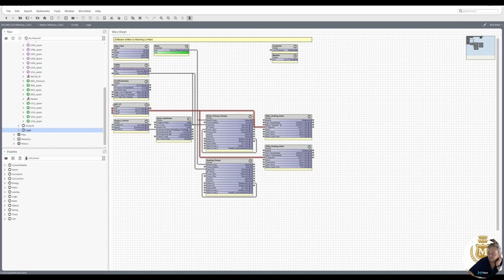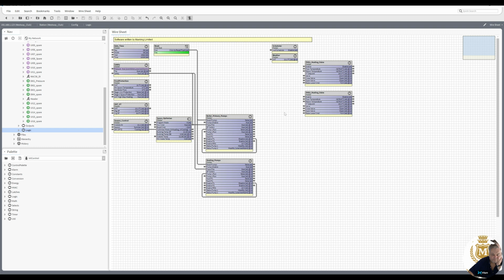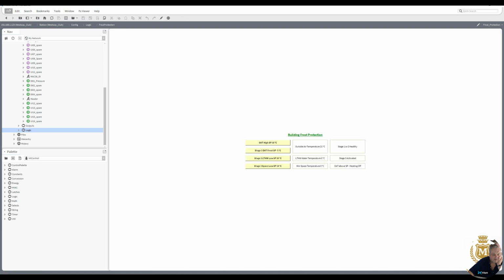We have no VT valves at all anymore now, so let's cut that out. Let's cut that out, and let's just move that out of the bloody way. Boiler VT pumps come on outside above 18, below pumps off. So we could actually use that. Outside air stop heating, we could use that block there.